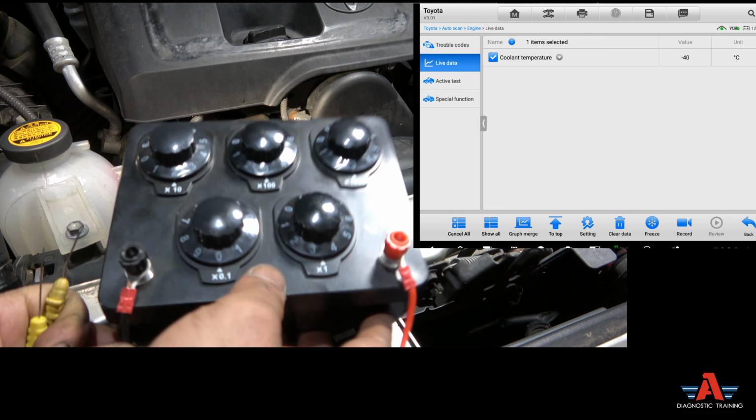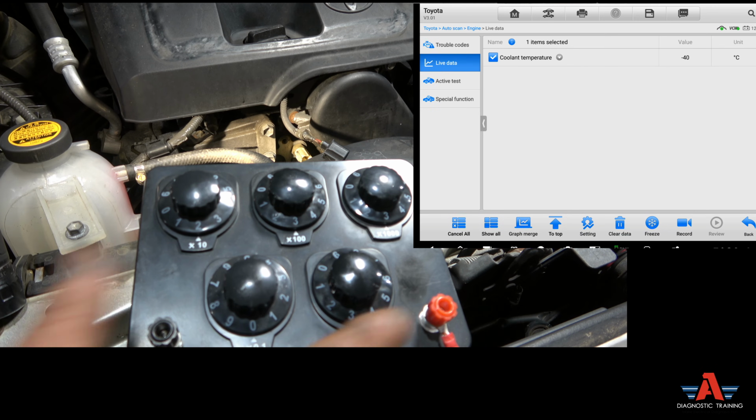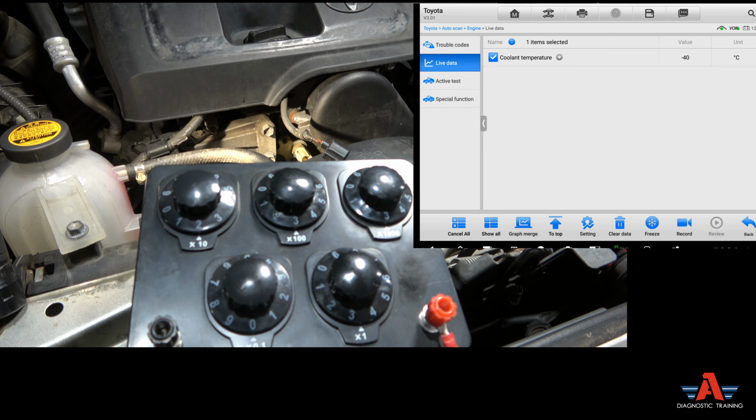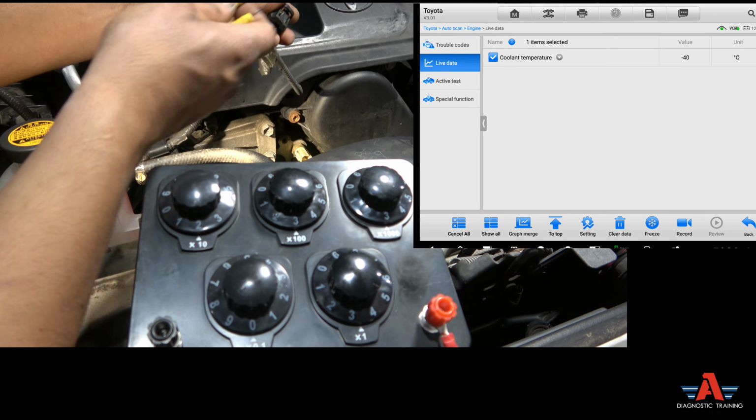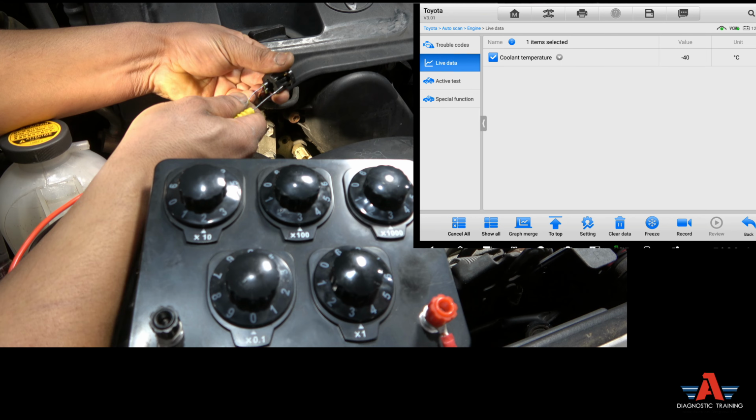As you can see, I've got 2 leads coming out of there, a red and a black one. Basically I'm going to do a bypass. I've already shown you on the board, I'm just going to show you quickly here. For this one I might just back probe this so the wire will stay there intact.